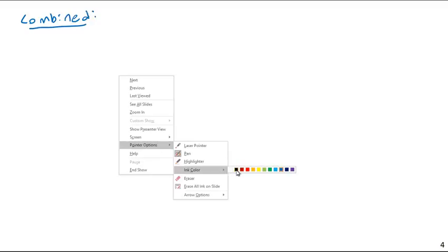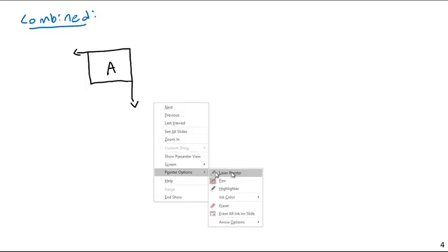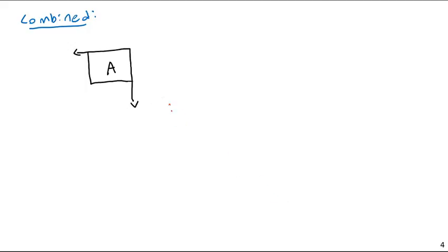Okay. Anyway, so now let's look at the combined loading. I'm going to have the same element here, but I'm just going to superimpose the two stress conditions on top of each other. Stress is combined by the simple principle of linear superposition, so you can just combine them together. Stresses acting on the same piece of material will just apply linearly, directly on top of each other, a simple summation.